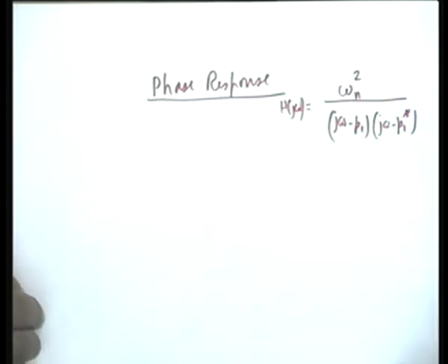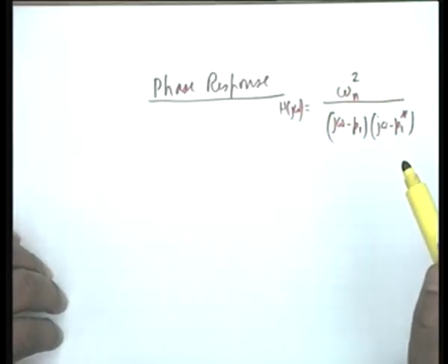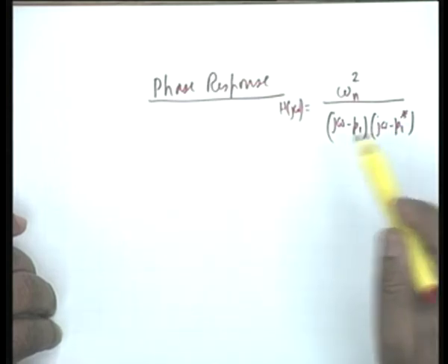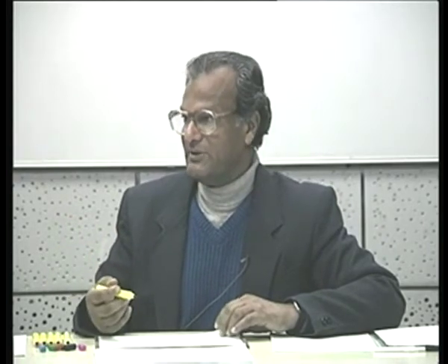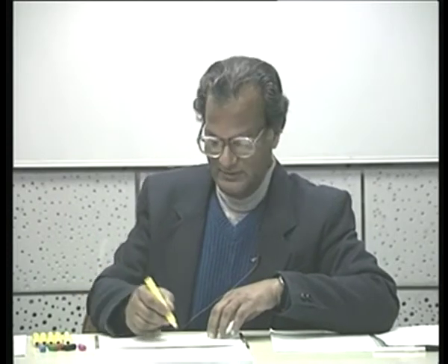I can of course substitute p1 and p1 star and do it analytically. I can find an expression for the phase response. But if you go from the mathematical expression, the chances of making a mistake are much greater in the case of phase response than in magnitude response, because in the phase response there are ambiguities. 0 and 2 pi cannot be distinguished from the tangent of the function. All trigonometric functions are the same at theta equal to 0 and theta equal to 2 pi. A change by plus pi cannot be distinguished from a change by minus pi, and therefore a picture in the case of phase response is worth more than 1000 words, not just 1000.